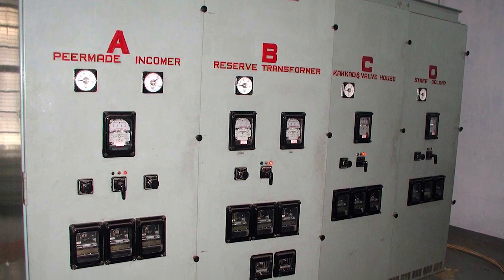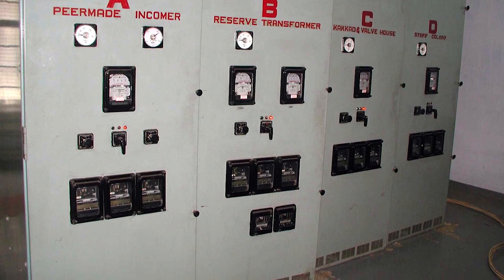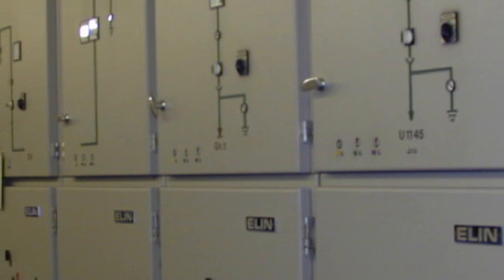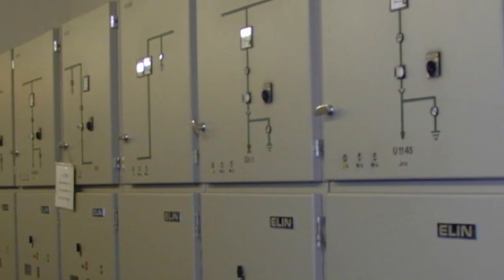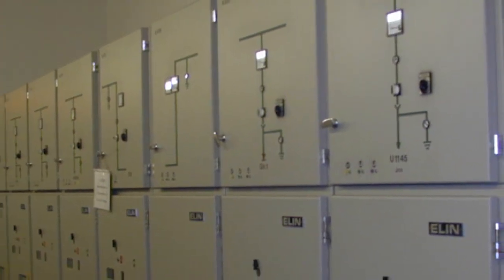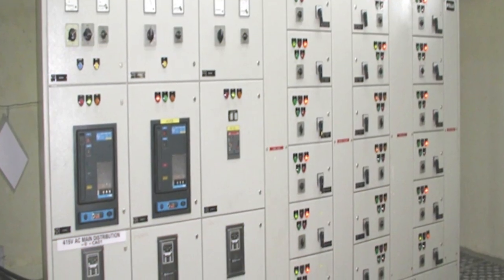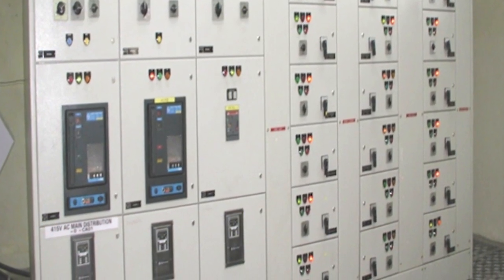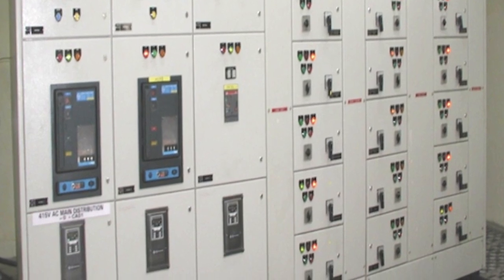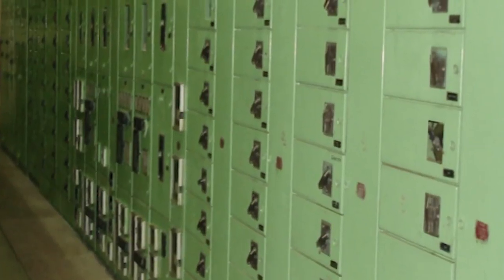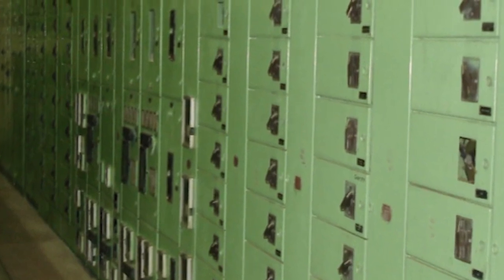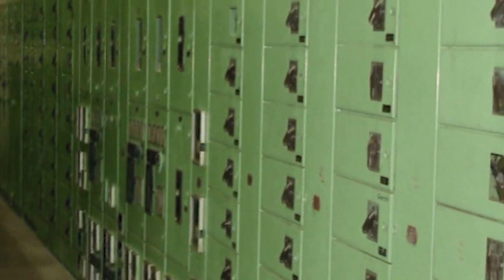MV switchgear. This distributes the 11 kilovolts, 22 kilovolts and 33 kilovolts power supply from grid as required by the power plant, and failure may cause blackout if no other power is available. LV switchgear. This distributes low voltage 415 volts AC supply to various electrical auxiliary, mechanical auxiliary motors, LDBs, switch yard kiosks and chargers. LV switchgear failure would cause blackout and no power to start auxiliary.